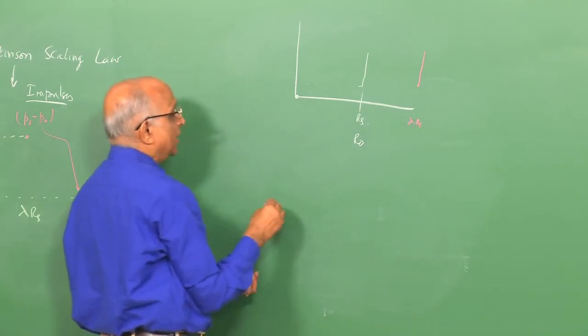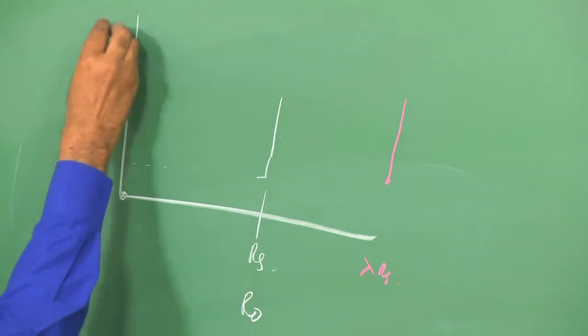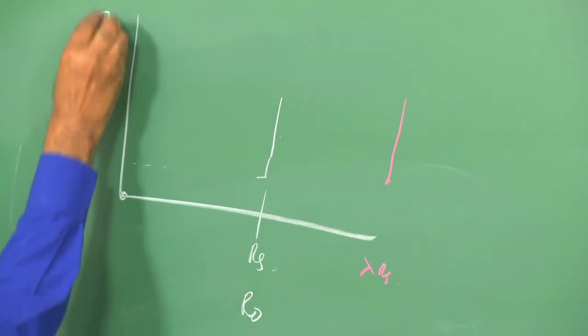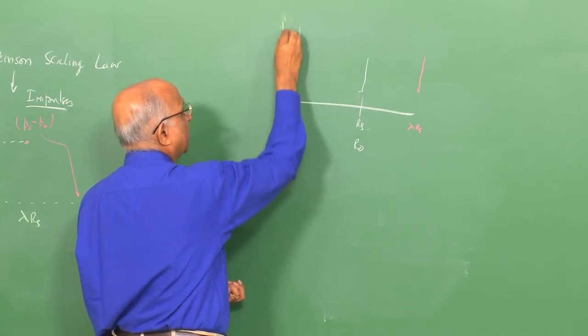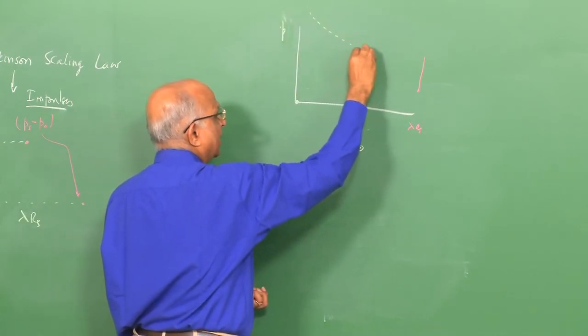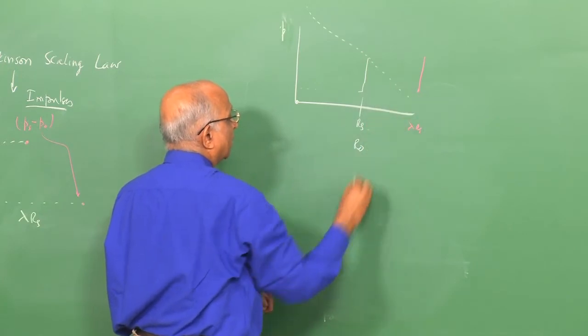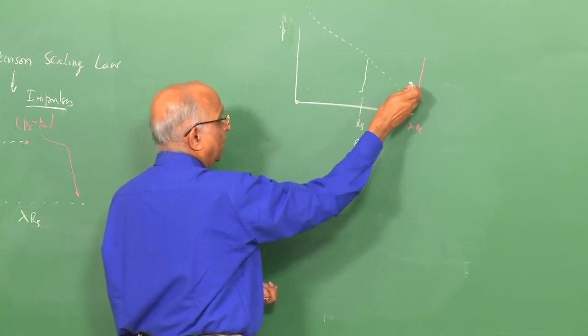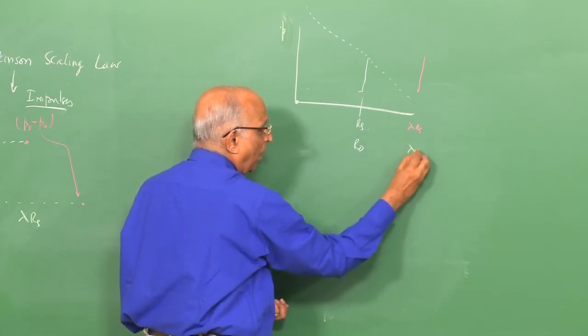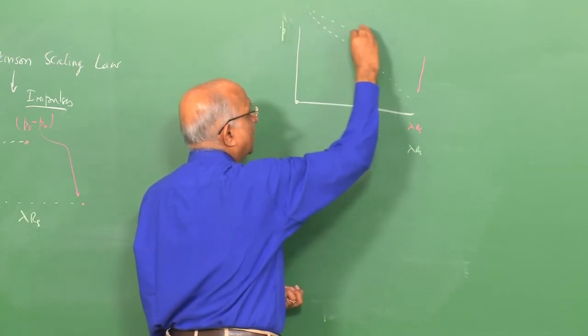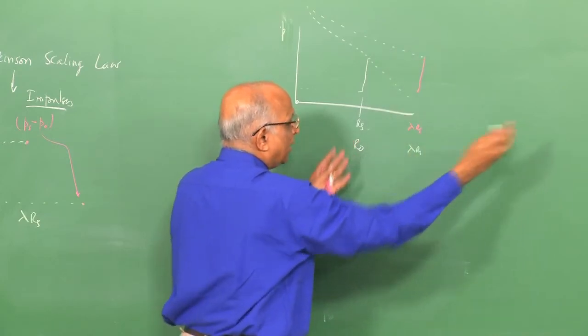In other words, in this case what is going to happen? If I take a look at r_s dot, or Mach number, or let us say the pressure ratio, I start with a high value of pressure and it decays like this. In this case, since I have increased the energy, or increased the value to lambda r naught, the blast wave will decay a little slowly, that means it will take a longer time.